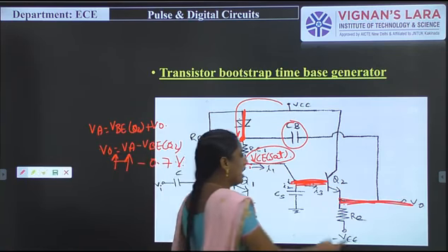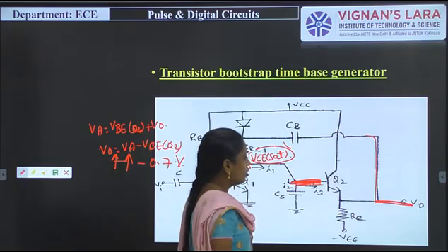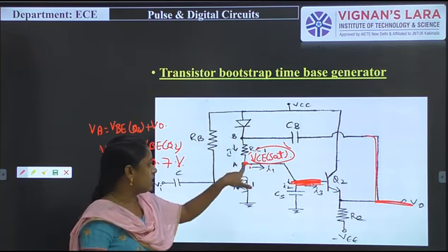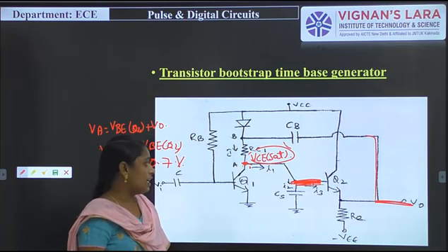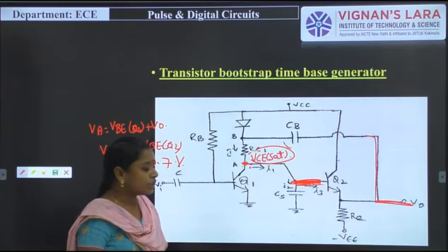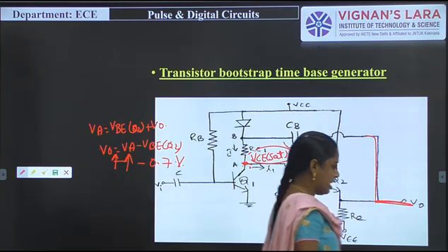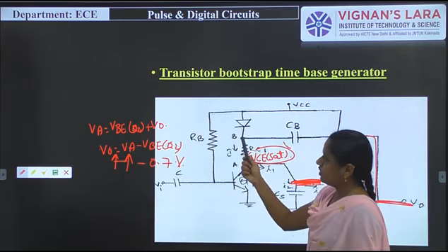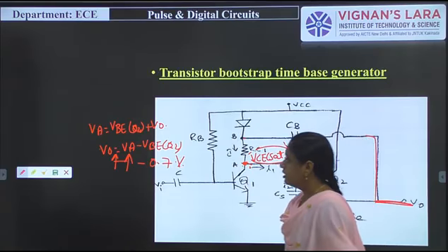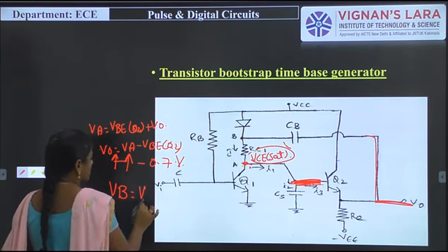This is given to the diode cathode terminal. In that particular condition, what happens? When a negative signal is applied to the transistor Q1, at that time the VA voltage will increase, and gradually this increased voltage also causes V0 to increase. This is applied to the cathode terminal of the diode, so during this time the diode is in off condition. Simply, we indicate that the VB voltage also increases, because the VCC voltage is coming here. VB is equal to VCC plus VA.